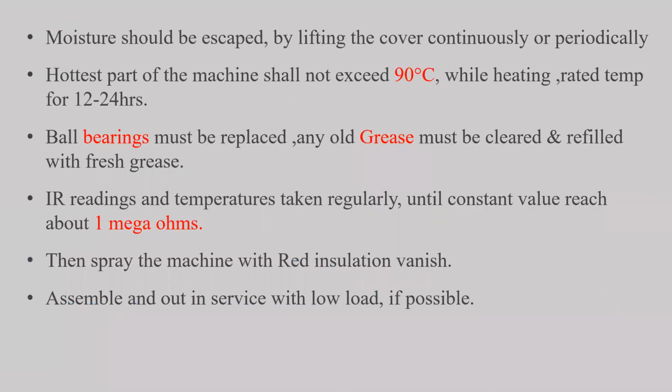Moisture should be allowed to escape by lifting the cover continuously or periodically. If we heat and keep it covered, sometimes water droplets will form. So it should be covered, and periodically we have to lift it. The hottest part of the machine shall not exceed 90 degrees centigrade while heating. This rated temperature has to be kept for 12 to 24 hours to check the condition of the machine, and it should not exceed 90 degrees centigrade.